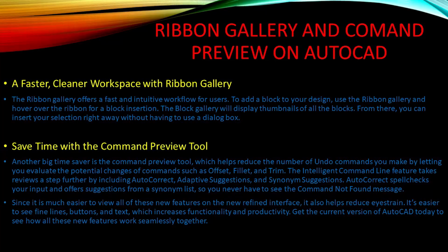Another big time saver is the command preview tools, which helps reduce the number of undo commands you make by letting you evaluate the potential change of commands, such as offset, fillet, and trim. The intelligent command line features take this a step further by including autocorrect, adaptive suggestion, and synonym suggestion. Autocorrect spell checks your inputs and offers suggestions from a synonym list, so you never have to see the command's not found message.